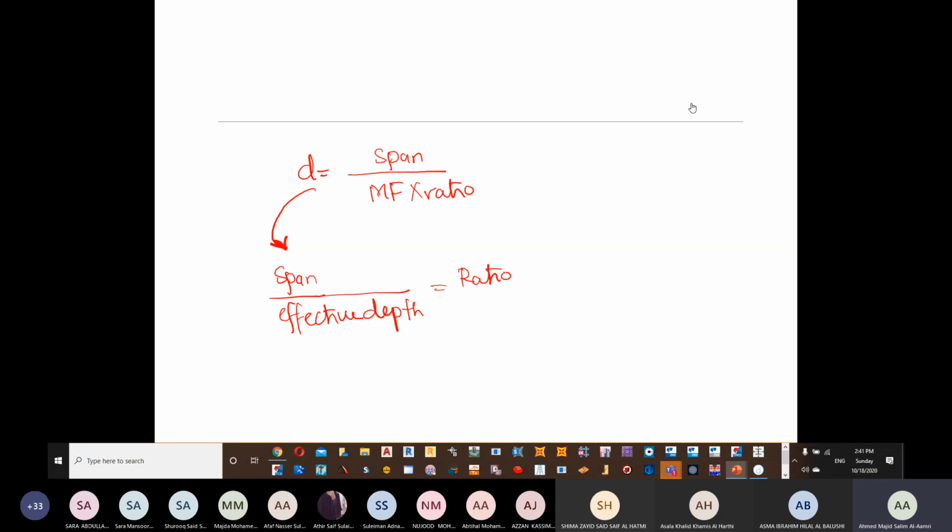Do you remember when I told you, when I said the different types of slabs, and I said like 6, 7 meters, 8, 5 meters? Do you remember these values? These values are derived from these equations only. So based on a certain span and that certain ratio which they found to be optimum, you should be having this amount of depth. Now, if you remember, we have cantilever for 7, we have simply supported for 20, and then we have continuous for 26.